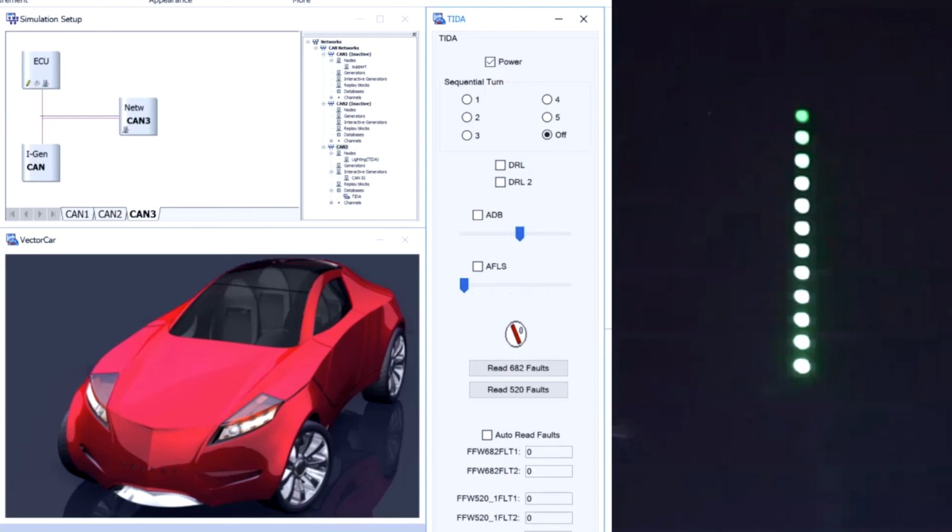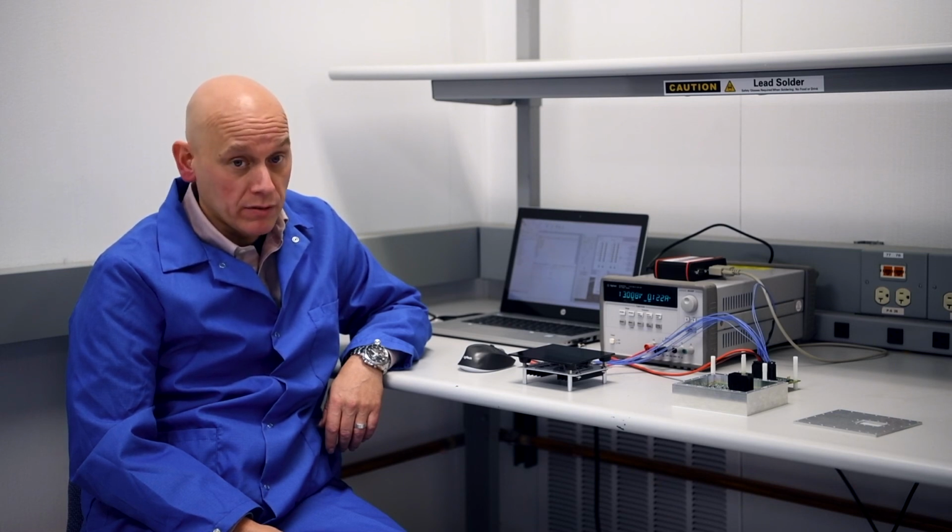Additionally, we can individually dim each LED using PWM dimming. Each individual pixel is dimmed with varying levels of PWM dimming to create a gradual light transition from pixel to pixel, creating a lighting gradient. As you can see through the demo, the two-stage boost and buck ECU is able to control LED current accurately throughout the load transitions during animated LED headlamp functions.